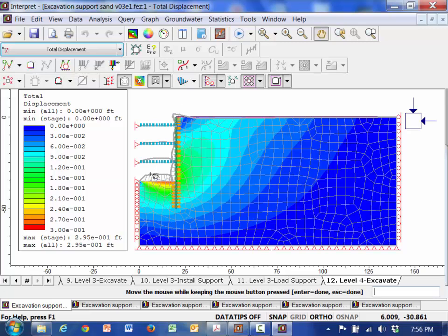Well, we can check the base displacement. We're generally more concerned about this. Ooh, I've got a bad boundary. I got some bad boundary conditions in here. I didn't see those. How did I get these fixed boundaries in these ones? We'll have to go back and fix that.